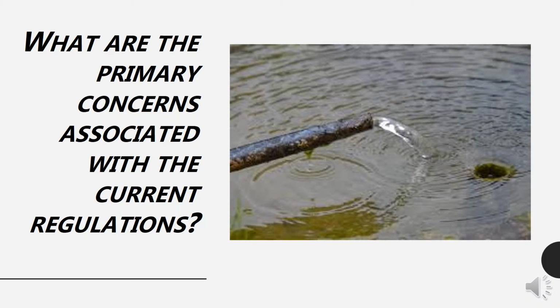The regulation of HAA5 instead of all 9 species is particularly important when considering source water with elevated bromide concentrations. When source waters containing high levels of bromide are disinfected with chlorine, DBP formation shifts to a greater proportion of brominated species, including the 4 unregulated brominated haloacetic acids. This means that the HAA5 measure underestimates haloacetic acid exposure, especially if the source water contains high levels of bromide.